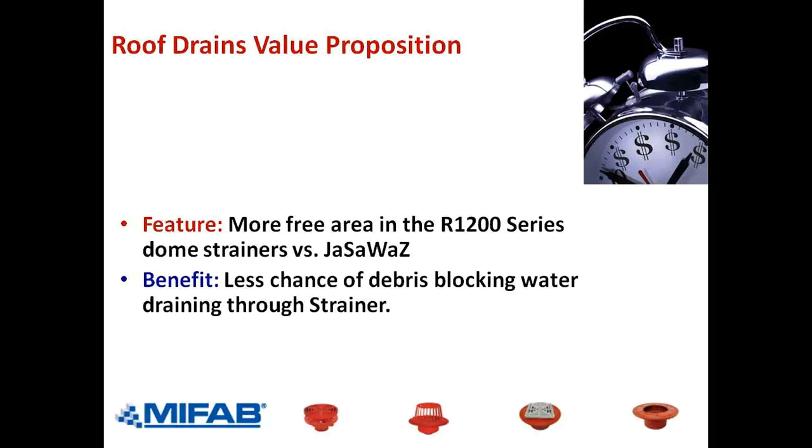You know, the worst thing that can happen with a roof drain is they get blocked, there's not enough of them, or they're undersized. Consequently, we could have water building up on the roof, and that is what leads to roof drain disasters, where roofs actually collapse because the water is building up on the roof.